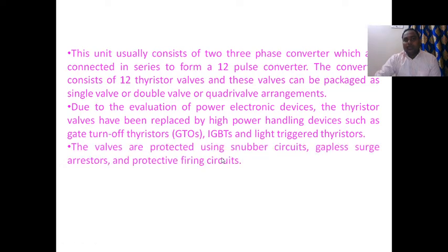The valves are protected using snubber circuits, gapless surge arresters, and protective firing circuits. The snubber circuit protects from over voltages.